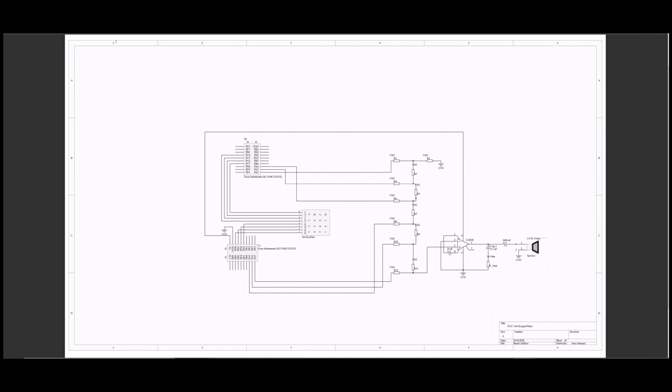When in piano mode, an input from a 4x4 matrix will play one of the 8 defined notes. This is dependent on which button is pressed. We begin by initializing port F so that we can use the onboard switch and LEDs. The LEDs will be used to designate which mode we are in.